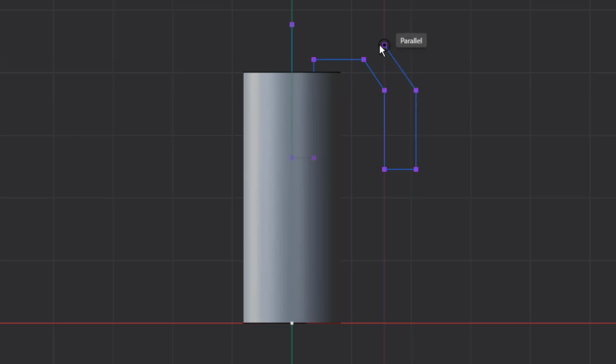We can left click and start to drag up. Now, if we want to go horizontal or actually vertical to this point and stay parallel to that line, we're going to hit this endpoint, hit Shift and let go. This will allow us to get vertical. And then I'm going to hover over this line, hit Shift and let go. And this gives me my snaps for parallel and vertical to that point. I'm going to go ahead and just bring this over, come down and close it off.